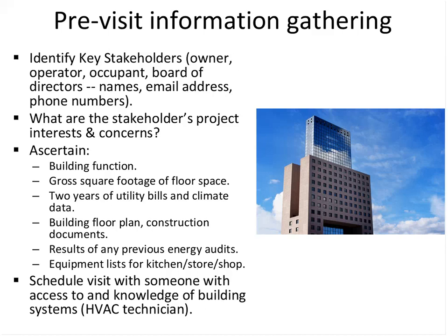And then you want to ascertain, basically, what's the function of the building. Pretty straightforward, but the other thing you may want to find out is, has the building changed use over its life? And that's fairly common in a lot of buildings. So it was built as a school and now it's apartments or something like that. You need to know what the building was originally designed for and whether they're using it today.